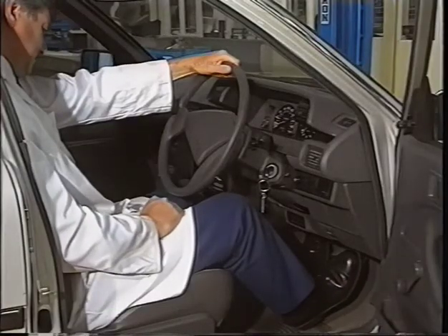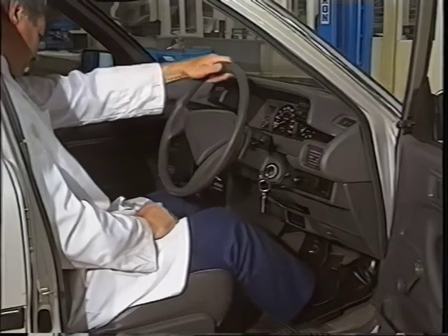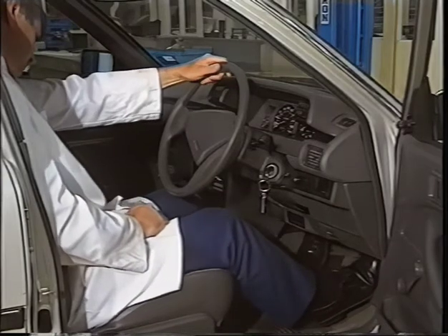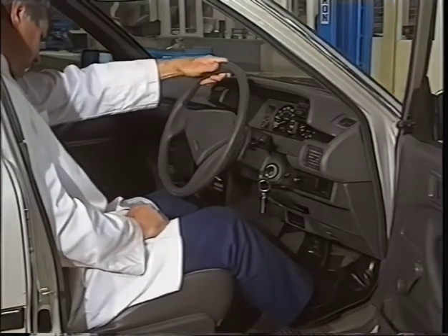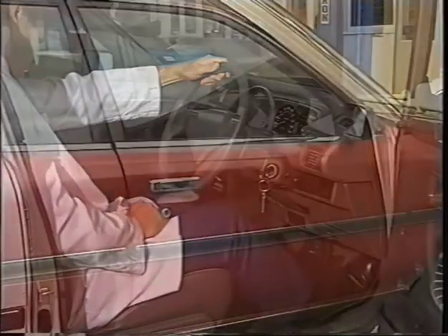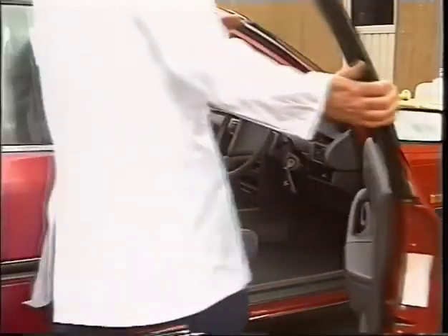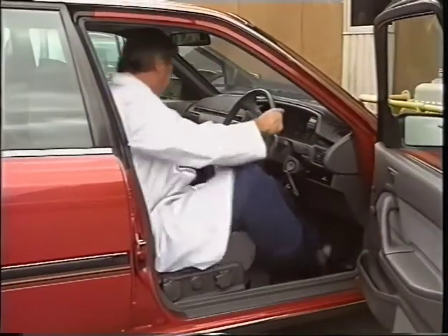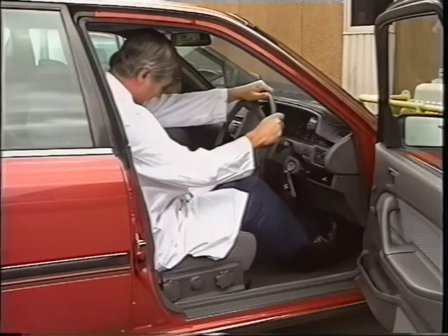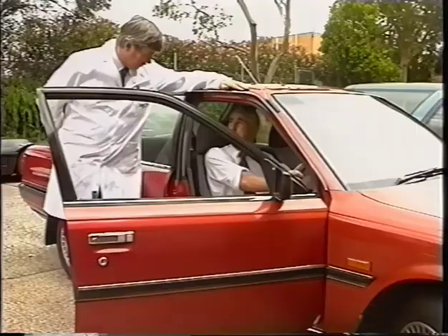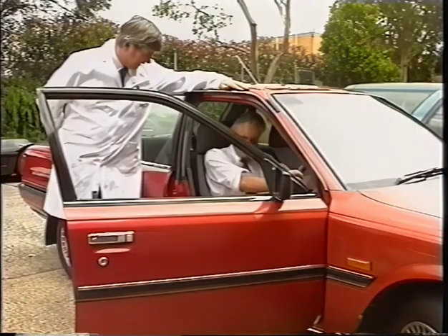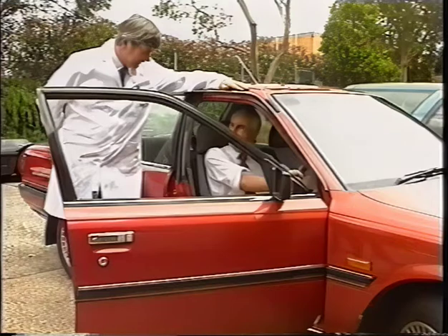The first step in any diagnosis procedure is to check that the problem actually exists and is not in fact normal for the type of vehicle being examined. If doubt exists, it is often helpful to perform a comparison with another vehicle of the same type and specification. A comparison can also be of assistance in demonstrating to a concerned customer that the condition is normal for that type of vehicle.